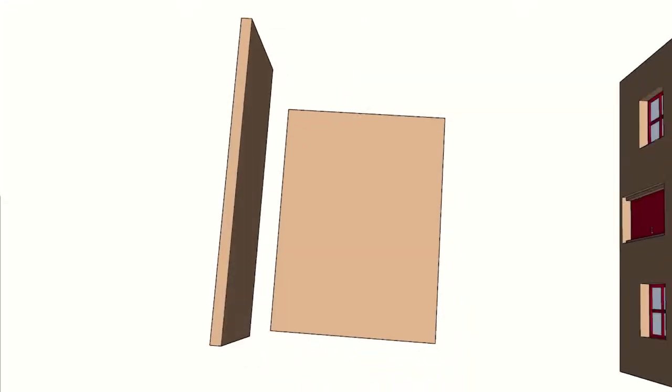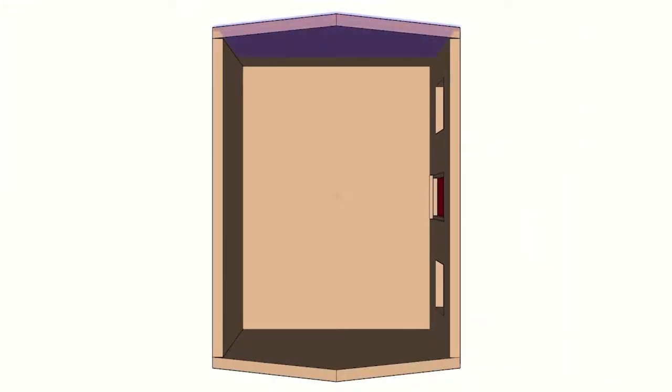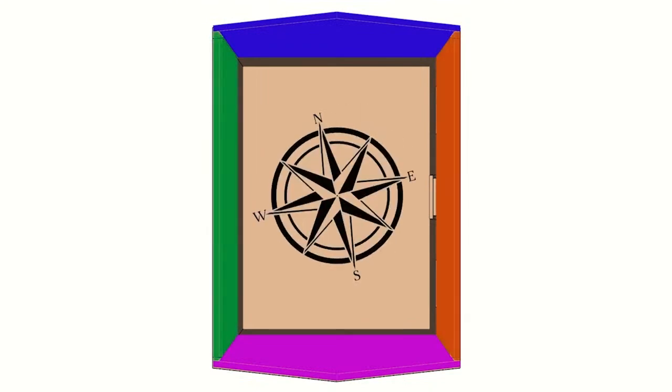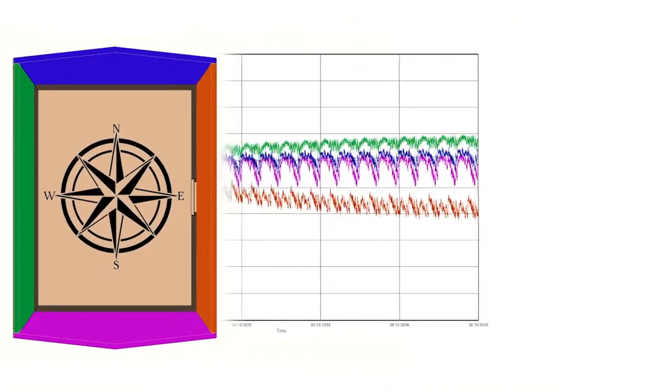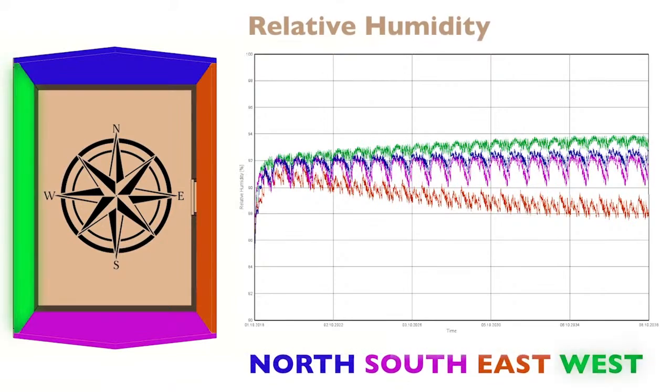The first step in this assessment is to run the model with no insulation to determine which area of the building has the higher inherent condensation risk, to establish which represents the worst case. If the upgraded structure is modelled using this element, it can be assumed that other, less onerous elements will perform adequately. We can see from the graph here that the west elevation has the highest predicted relative humidity, and therefore the highest risk of condensation occurring. So having established the worst case scenario, we can now move on to a more detailed assessment of the wall construction itself.